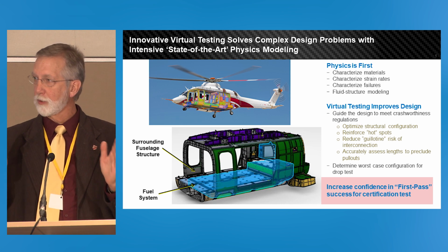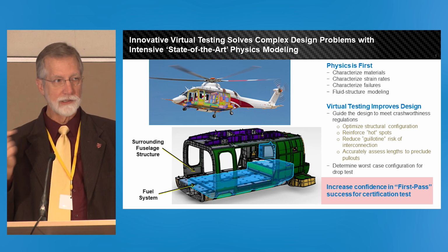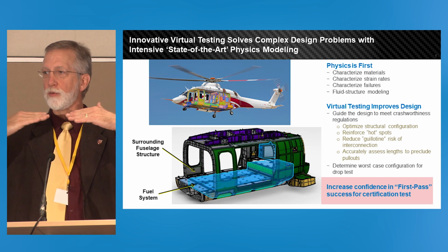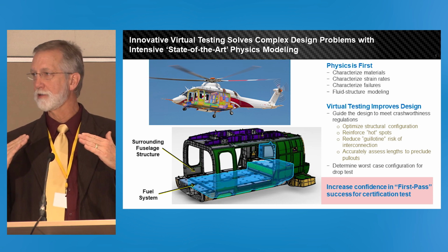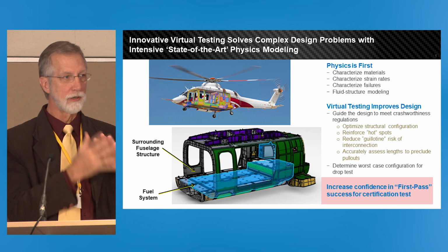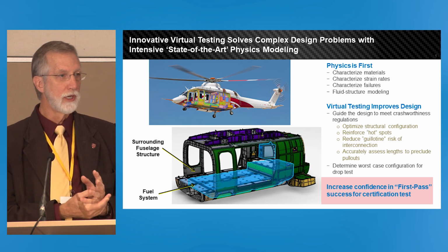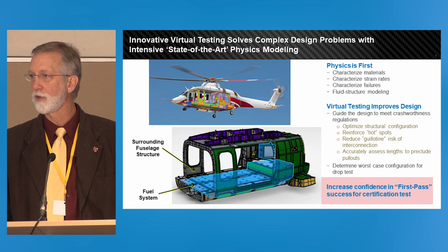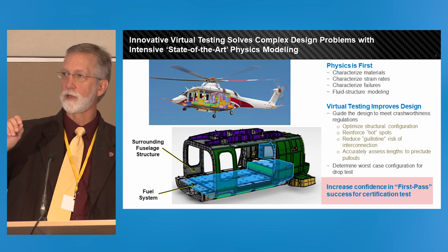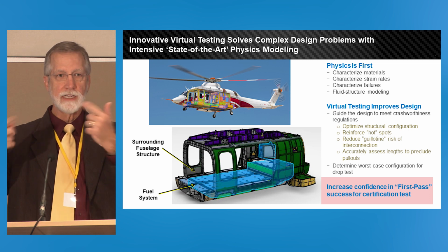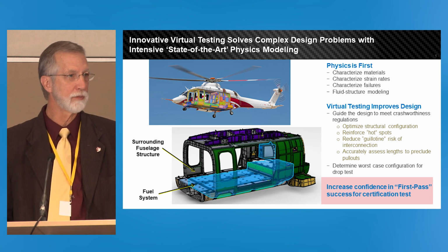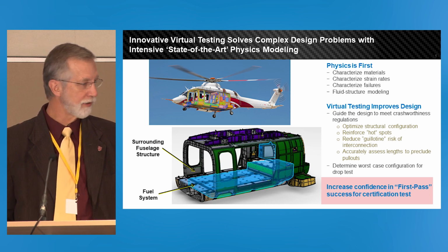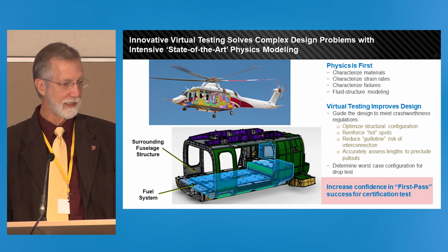Well, it's important, a couple of things. First, when the interconnects go through structure, you have the potential risk of a guillotine effect, where the tank, when it deforms down, can hyperstretch the interconnects, or the structure can actually close off or become a risk there. So just because you've sealed it, you need to make sure you also evaluate, is there any risk of failure of those interconnects? In fact, the fluid is still there, it's just blocked, and if it leaks on either side, you're going to still have leakage. So you have to check that, make sure that you still have a complete system that will not introduce failure risk. So this is a view of it.